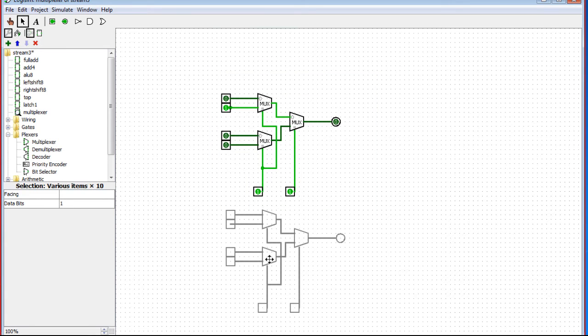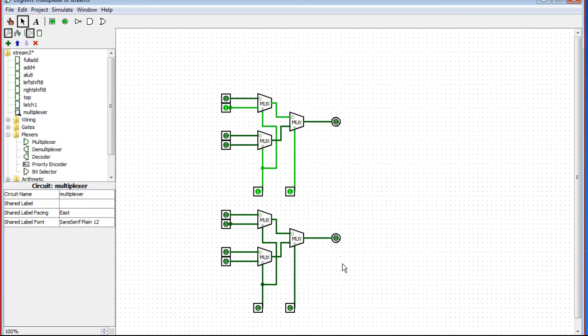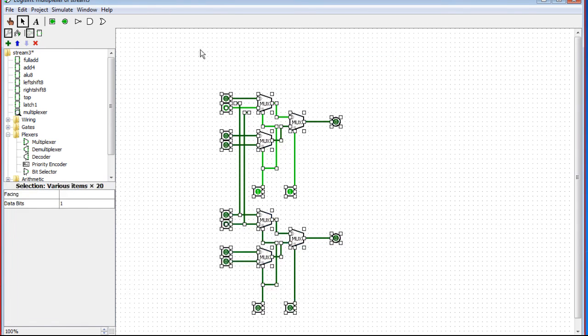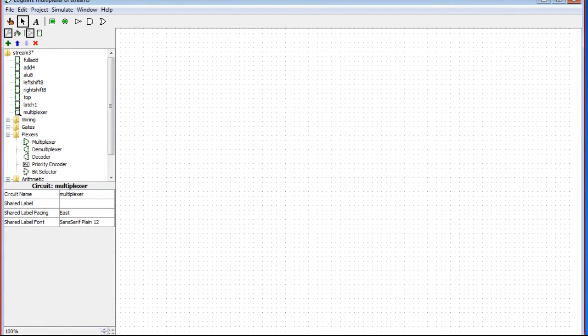All you do is line them up in parallel, and you put these ones together. These are going to be the 0 input, the 1 input, the 2 and the 3. You line them up like that. You arrange them in parallel. It's the same as with logic gates, right? You can arrange them in parallel for creating wider data bits, or you can arrange them in cascading, and that'll give you more fan out, more inputs. It all works the same.